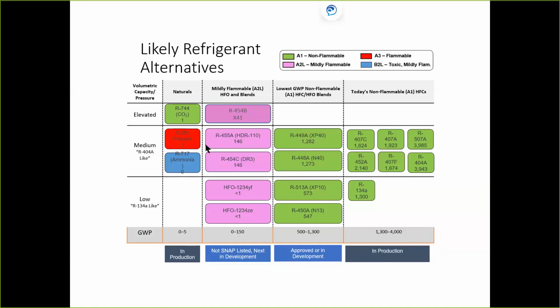And the reason I say knee is that versus air, it's a 1.52 in weight, identical to CO2, by the way. So the gases are going to drop to the ground, okay? So your detectors inside the mechanical room are probably going to be somewhere around 18 inches off the ground. And I foresee, possibly, as fast as 290 is growing and getting traction in the industry, you may have to wear some kind of alarm system with a Velcro strap that you strap on before you enter the mechanical room. I'm not sure yet. We still have a lot to learn about this refrigerant, so stay tuned on that.